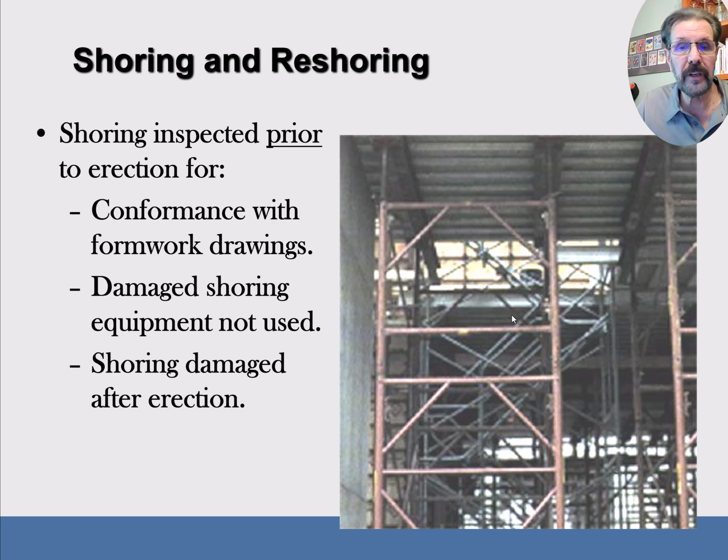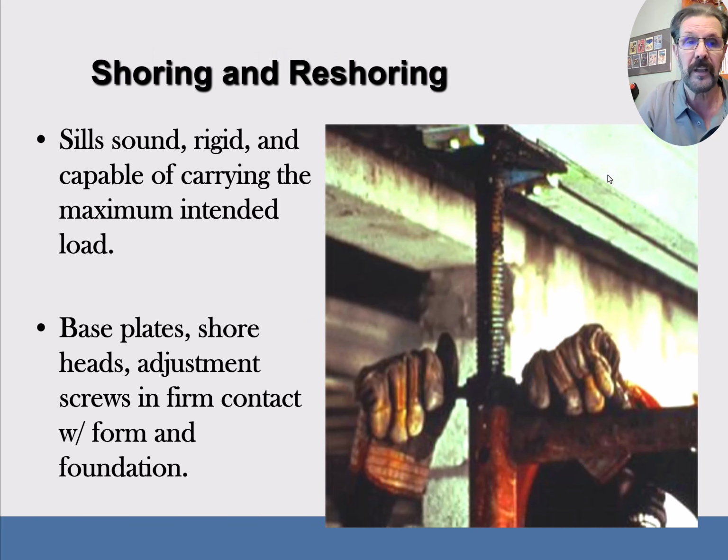Shoring and reshoring, you know, the idea is that when you start having a whole bunch of steel beams, and you're holding up corrugated steel decking like you see up top here in this picture, then you start pouring concrete. That concrete doesn't add any strength to the floor system at all at first, because it's just dead weight, and it can cause it to droop. And so what we do is we put a whole bunch of little mini columns in there to hold it up temporarily until the concrete has gained strength. And once it's gained strength, it's got that exoskeleton at the bottom of the corrugated steel decking that it was poured against.